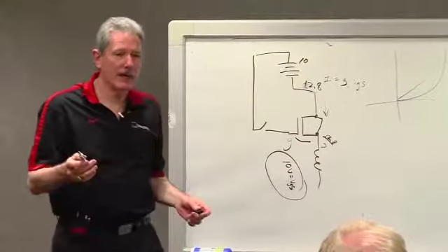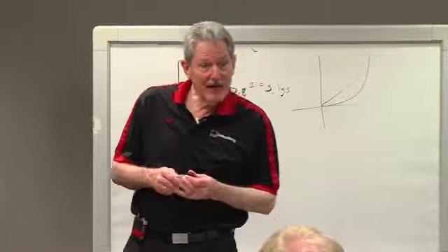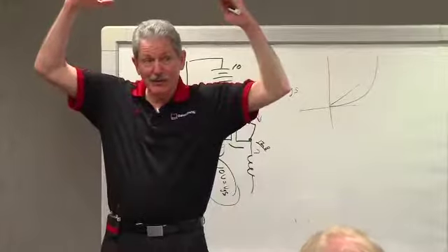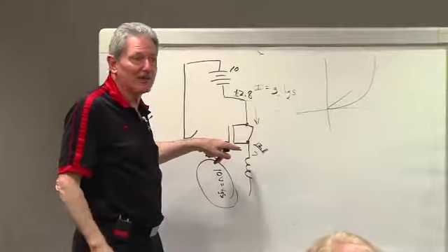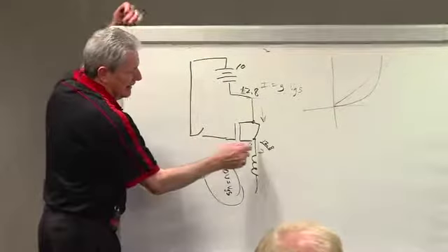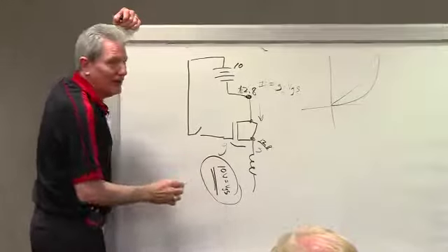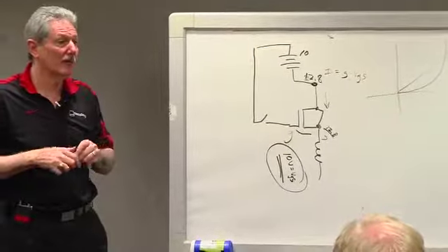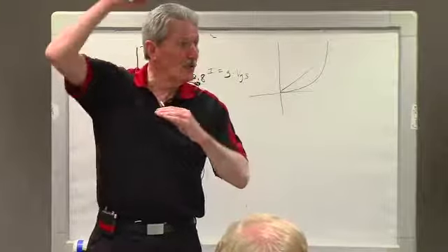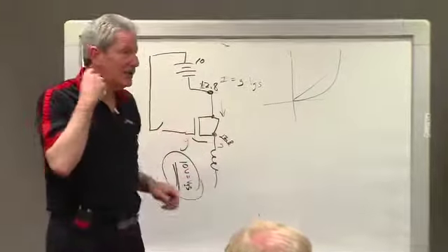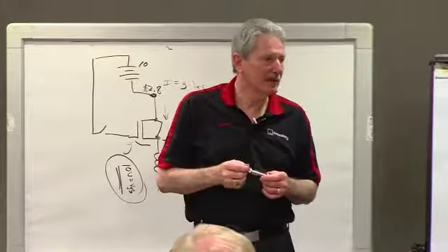That's why all of the regulators have voltage doublers or charge pumps, because you have to take the voltage above the highest voltage that you've got. If you don't do that, you have high power dissipation because of the fact that this potential is at this potential and I need 10 volts to turn it on. That's why on the MOSFET rectifier bridge, you have to have a charge pump. On all the voltage regulators with a high side device, you have to have charge pumps. All of that stuff costs more silicon.